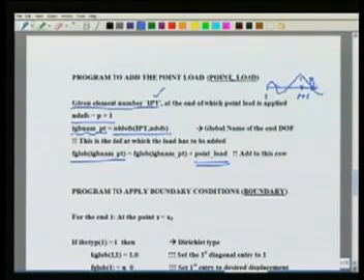Once we have this, we have taken care of the point load, and here we have decided to add only one point load. You see that an extension of this to take care of multiple point loads is also not difficult. We have to find the locations of the point of application of these loads, find the corresponding elements at the extremity of which each is applied, and then simply find the global degree of freedom corresponding to this extremity and add the value of the point load to that corresponding load vector entry. So this is how we will take care of point loads.